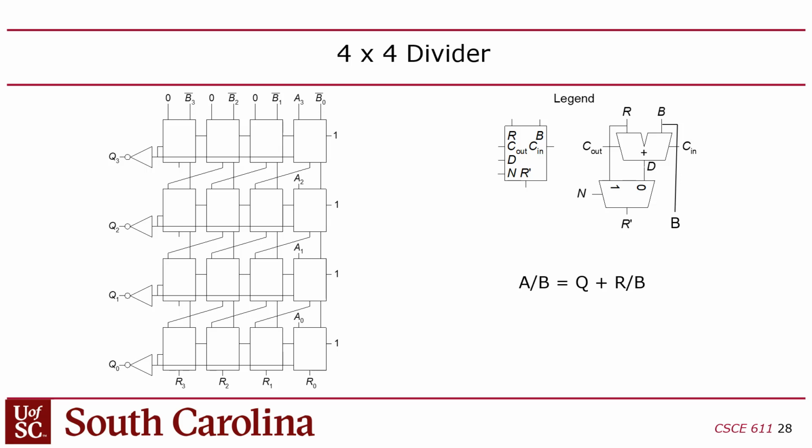So the problem here is that a divider is going to require subtractors, right? A 32-bit divider requires 32 subtractors, but not only that, it also has to have the restoring logic too, the comparison, the comparator, and the restoring logic. So a divider is expensive. When I first started developing this class, we put a divider in your ALU, and we couldn't make that happen because it used nearly all the logic on the FPGA, right?